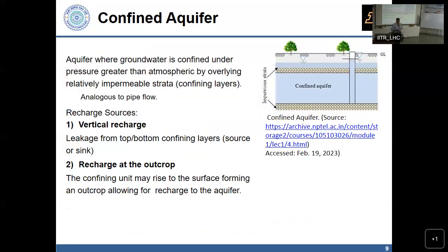Yes. If it is penetrated totally, the pressure will be different. The height to which water could rise could be different, depending on the nature of flow in the main confined aquifer. If you do not have significant vertical gradients, then the pressure is approximately the same throughout. However, if you have vertical gradients, then what you say is right. Depending on the extent of penetration, where the well is being screened, that will determine how high water will rise in the well.